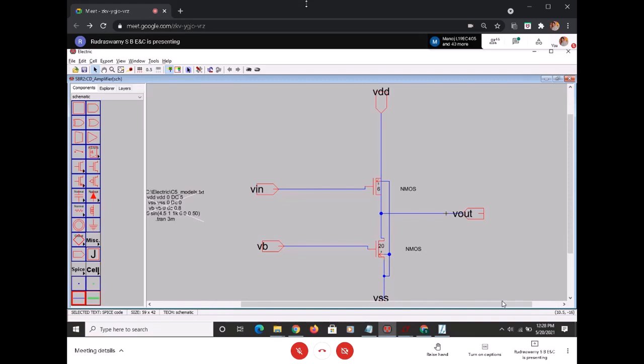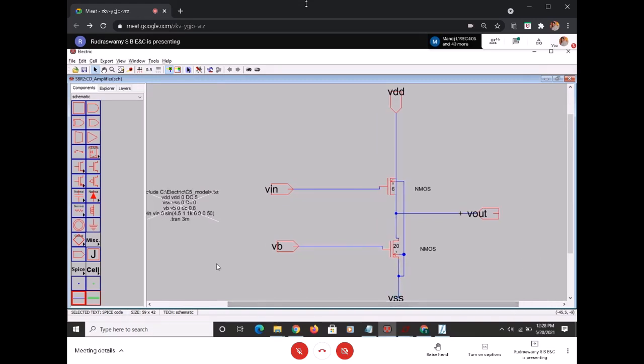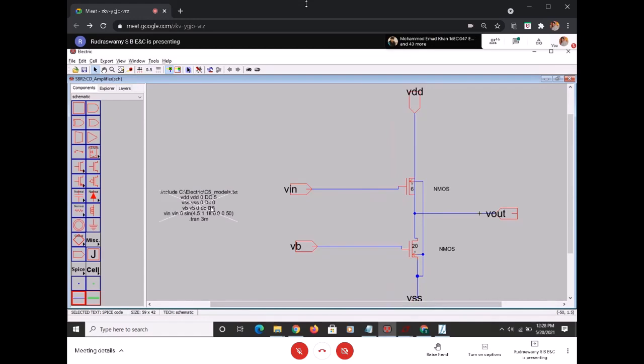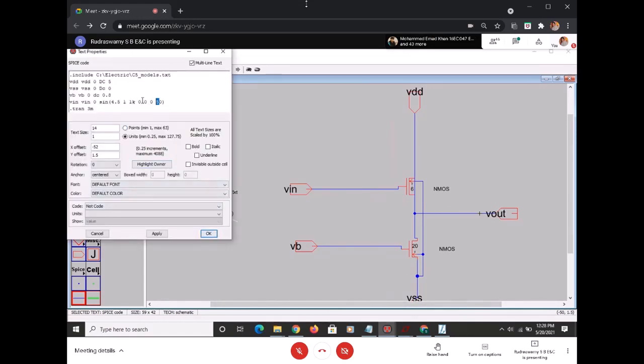You see from which voltage onwards V out and V in are parallel. Once you get that, you can do your transient analysis, and in a similar way you can finally do the frequency analysis with AC. For AC, what we give is in terms of decade, 100 steps, and then 100 G. Is that what you have to specify for the AC analysis?